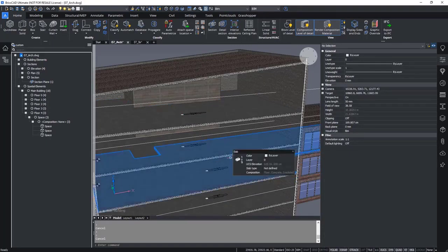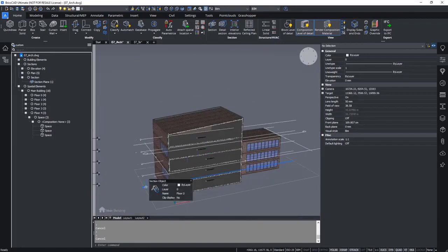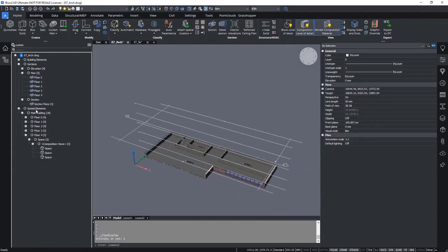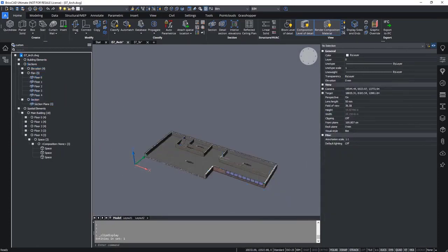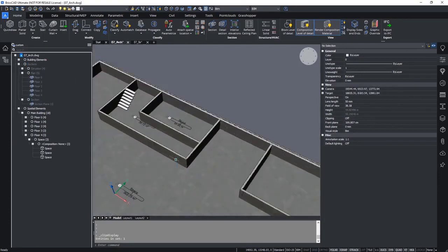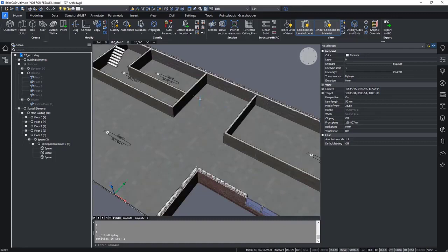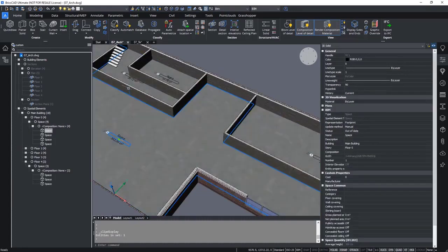And then we will see how to update the model and the spaces. So we will clip the horizontal section of the first floor. We can hide the sections for an instance. And then we see that here we have two different rooms. Let's suppose we want to create a third room in the middle here. So now the space encompasses this extra protrusion as well in the space.